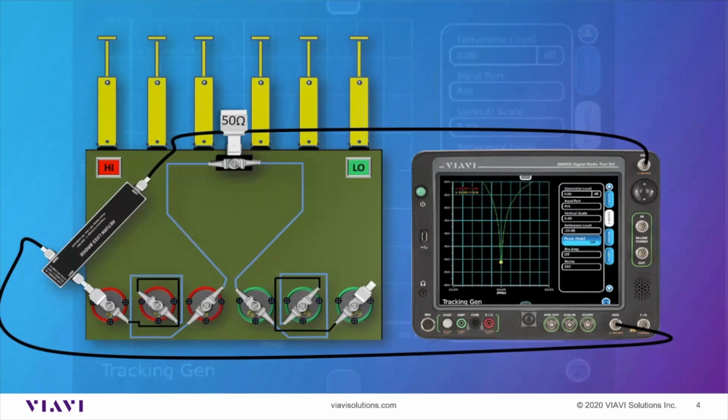And if I wanted to, I could go back and go through our process again of putting our load back on our opposite side of the duplexer, and then check that insertion loss again. But I think I probably did that, but it made very little difference because I was making such small movements in those plungers.